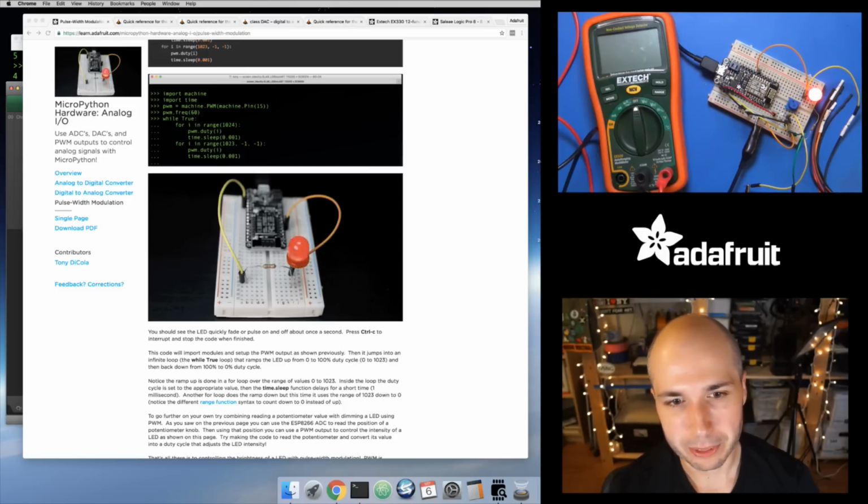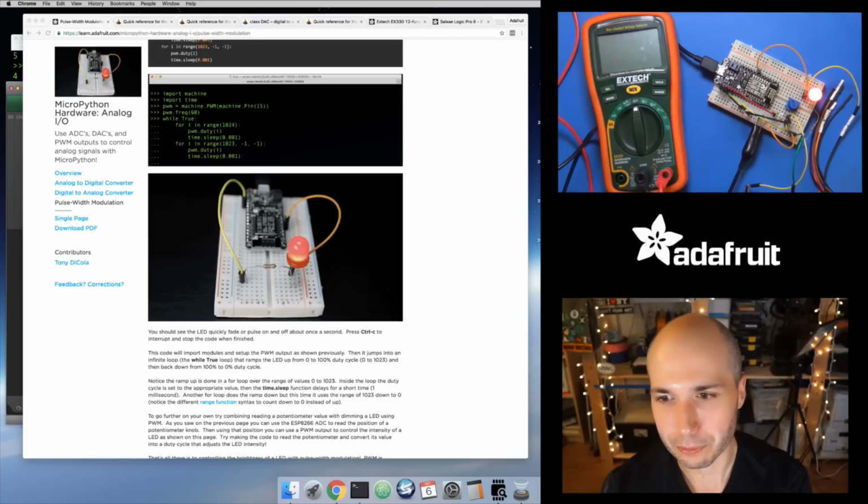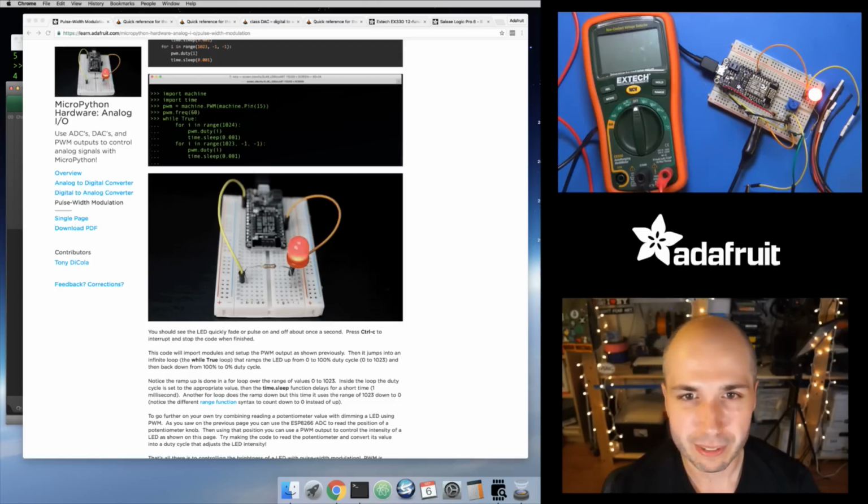It has a programmable gain. So if you're looking at a small signal, like if you have a load cell, which is what you use to measure weight, usually you get a really small voltage out of that, and you need to amplify it a lot to get it into that range that your analog to digital converter uses for this. So let's see, what else is in here? Yeah, the MCP4725, that's another one, I guess it's a DAC. Oh, interesting.